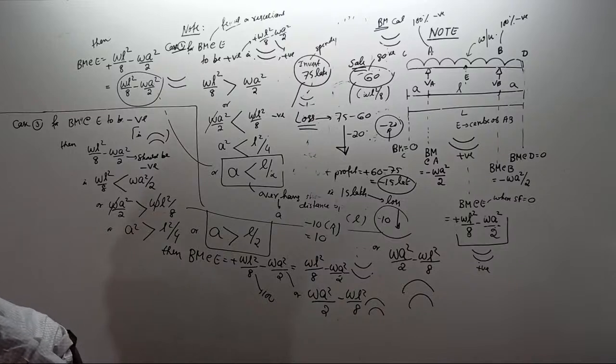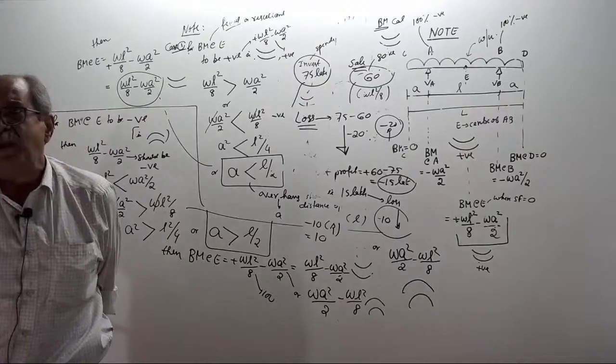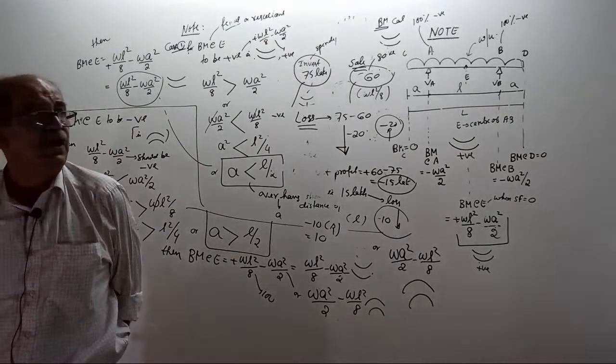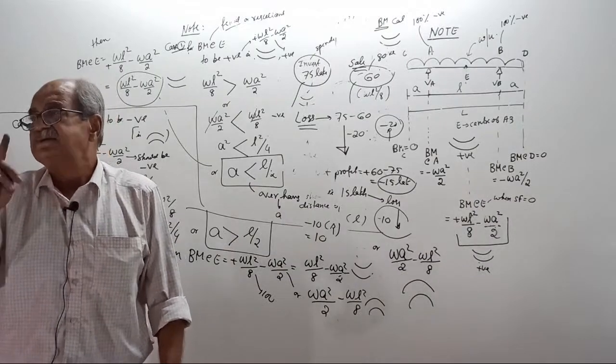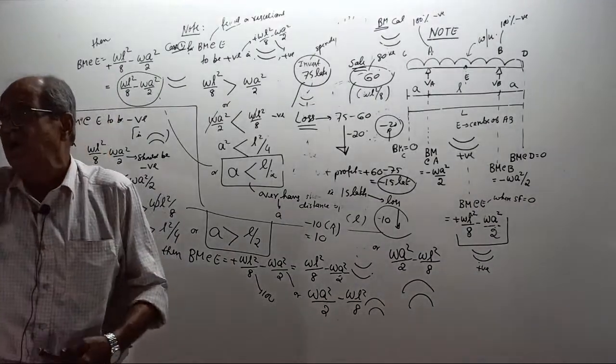Without sign, they want to show only 20. Then tell me, in what direction should they show it? Upward or downward? Think fast, a little. You are not answering it. Upward is positive, you typed minus 20 because the load is downward. When you type minus 20 in the SFD and BMD or everywhere, STAAD.Pro should show a downward load of how much?